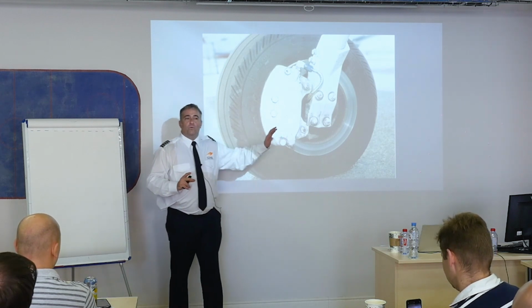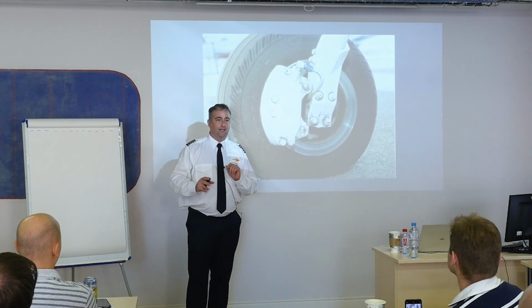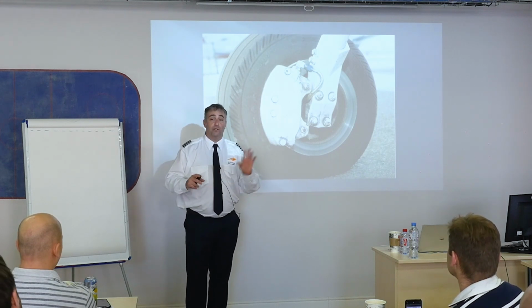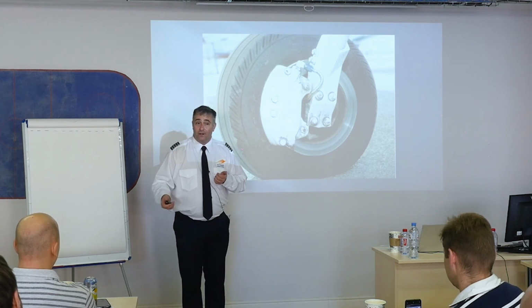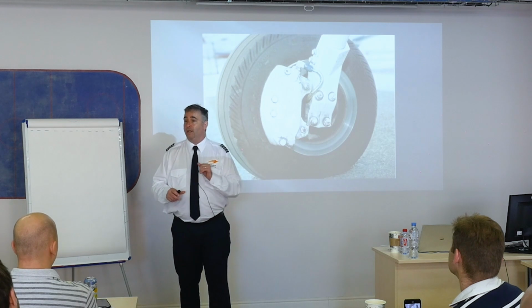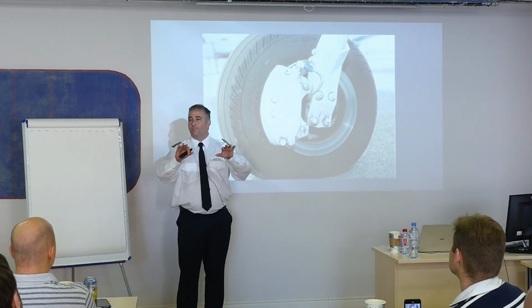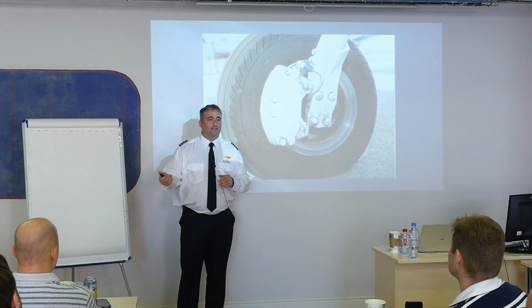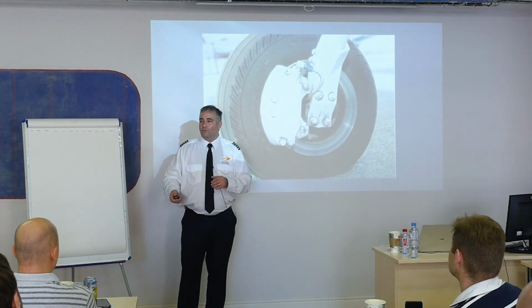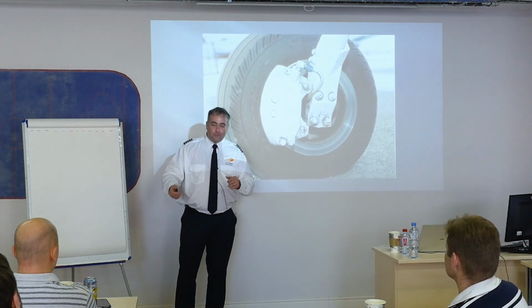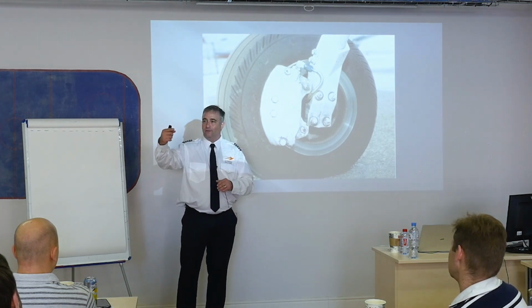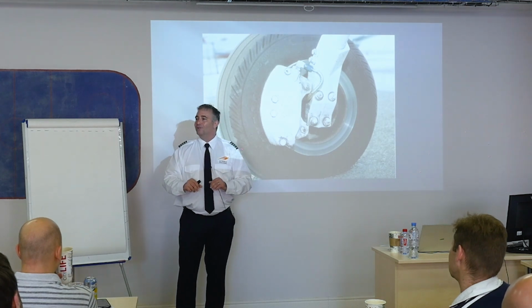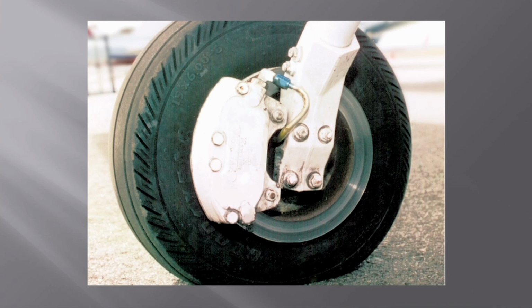The other thing is, when you're taxiing, not the taxis, Uber and all that, but when you're taxiing the airplane out on the ground to your runway, don't put your feet on the top of the pedals. I see it all day long. You've got the airplane at 1,500 RPM, making all kind of noise, and the airplane's barely moving, and they've got the brakes on. Don't do that. You're just putting a lot of heat on the brakes. If I need those brakes for a rejected takeoff, they're not going to work as well as they would if they were cool. All right, a couple things about brakes and brake systems.